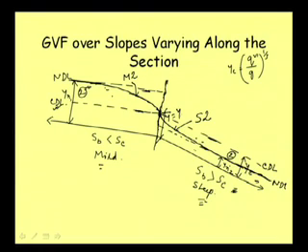And when we talk about computation of the profile, what we will have to do at this section, we know that y is equal to yc. So that is our known point, and from this we can compute this profile up to yn at different points, and then from this again we can compute this profile up to yn at the downstream point.